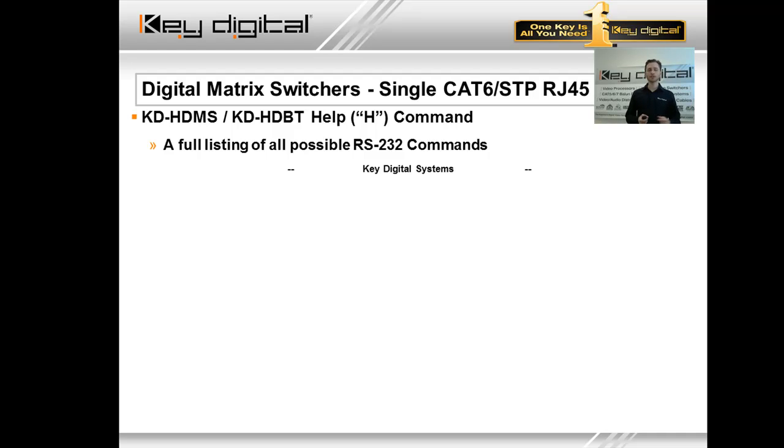If we hit the letter H, we open up the hyperterminal software, for example, we enter the baud rate of either of these products, which is 57,600. We leave it at 8, none, 1. We set our flow control to none, and we go ahead and apply that setting, and we have now the blank white window of the terminal software. We're all familiar with that, hopefully. Hit the letter H. Here's what comes back.